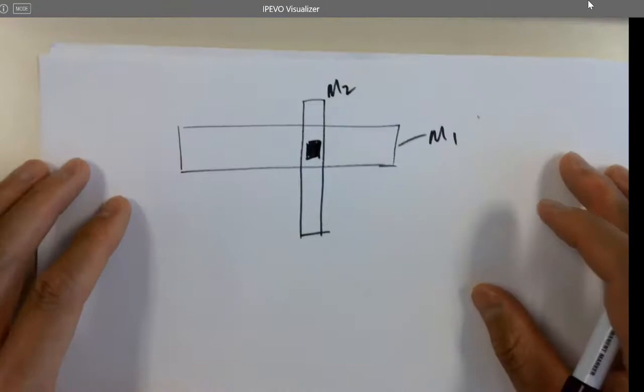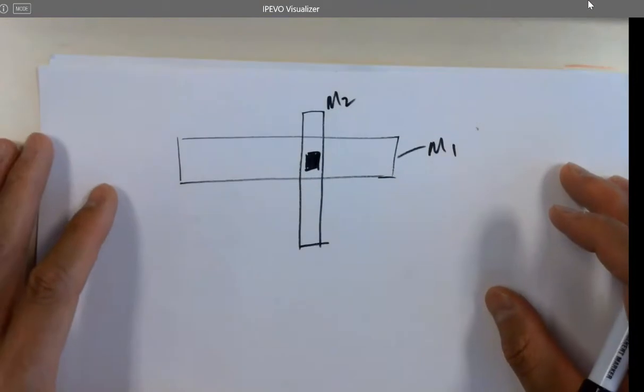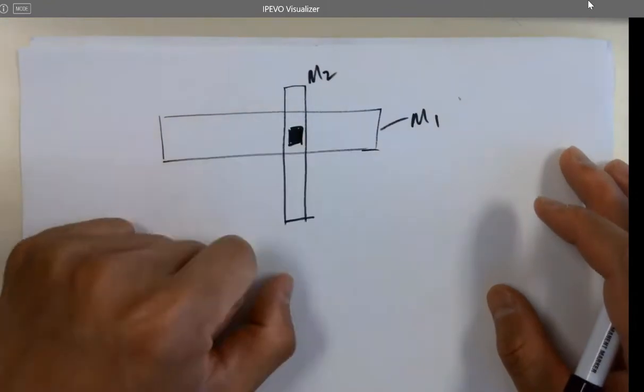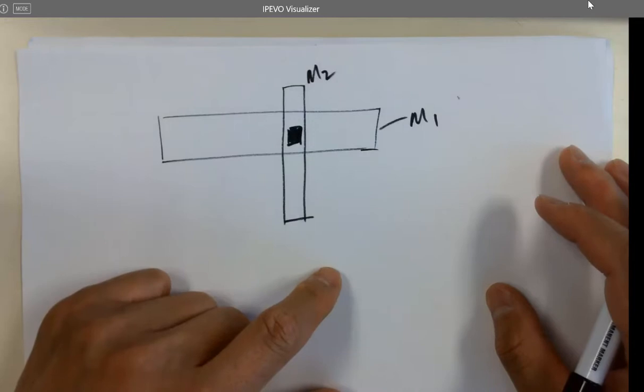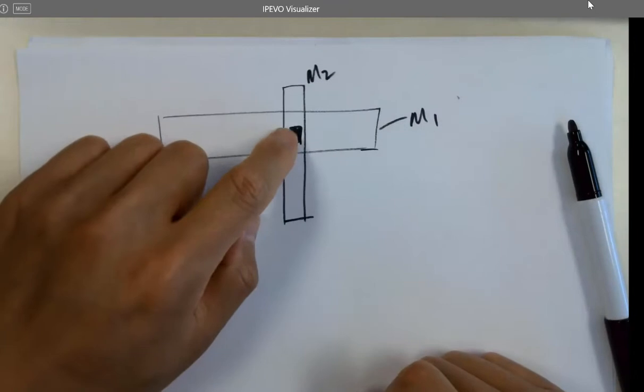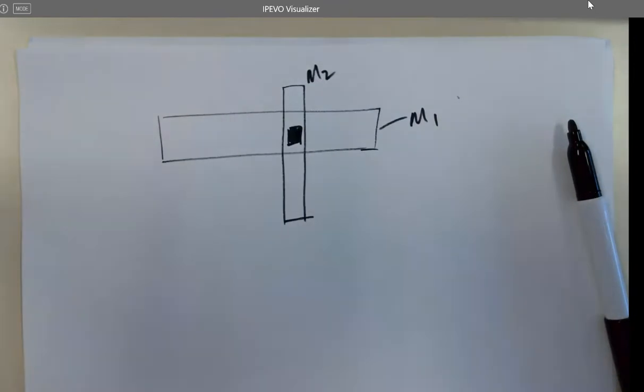Are they shorted together? Yeah, that's a via. If you don't have the via, then they're not. They're just 2 different layers. They're not shorted together. You need a via to connect them together. Even though you have them crossed in the layout view, they are not shorted.